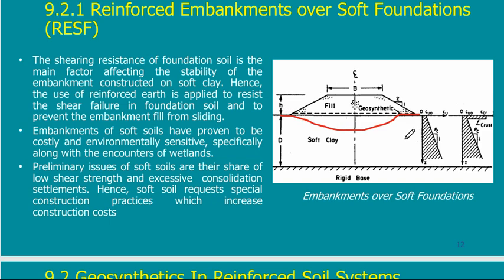So what can I do to prevent this? I can just add here a layer of geotextile reinforcement, grid reinforcement, anything that we have just said, we can put it here, and this would help as if I am putting a reinforcement below this embankment, so it helps in redistributing the stresses, so that the stress coming to the soft clay would be redistributed on a bigger scale, and the settlement would be reduced.